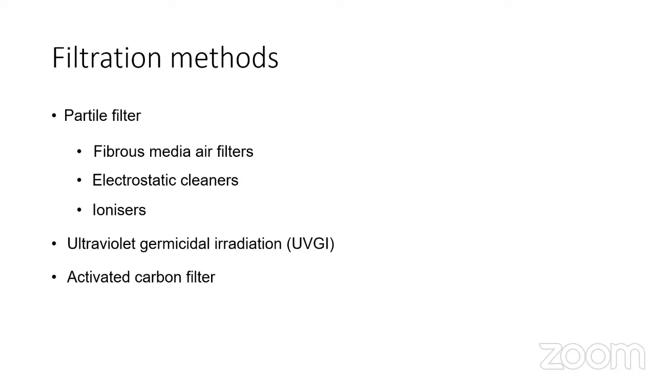Sorbent media basically remove gaseous air pollutants by getting them deposited on the media by the process called adsorption, or convert them into harmless byproducts using a combination of physical and chemical processes. So basically there are no harmful byproducts when using an activated carbon filter or similar adsorbent media. That is one advantage of these filters.